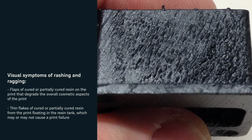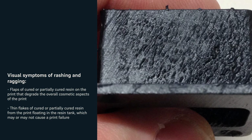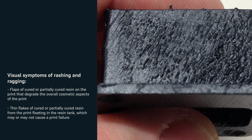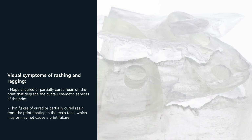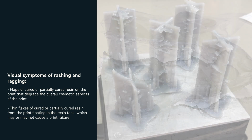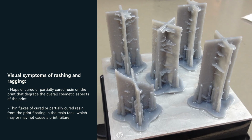If your print exhibits rashing, one or more surfaces will be rough or bumpy even if they were intended to be smooth and untextured. A print exhibiting ragging will have bits of cured or partially cured resin hanging off of it, forming thin, shelf-like structures. These structures, also called flaps, can detach from the part during printing. Once these flaps are floating in the resin tank, they can block the light's path and cause print failures in subsequent layers. Ragging and rashing can both be caused by contamination on an optical surface in the printer.